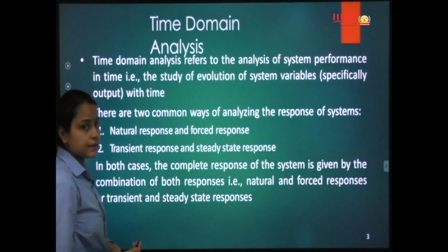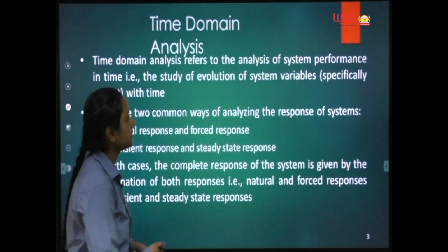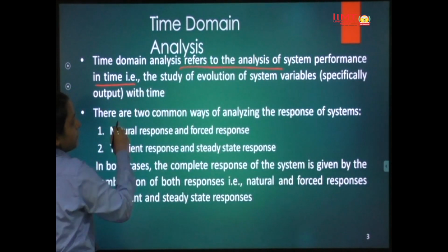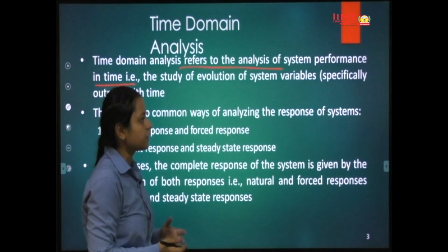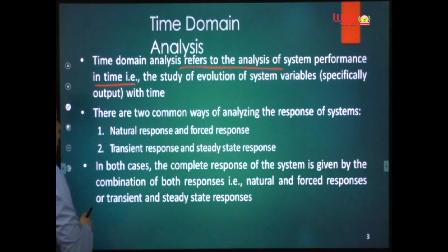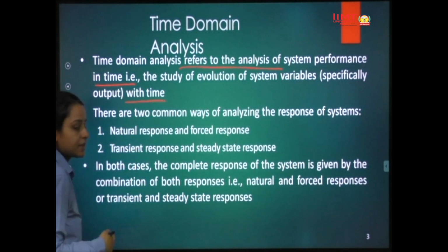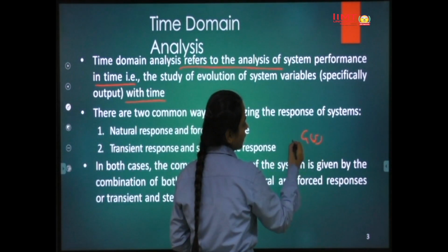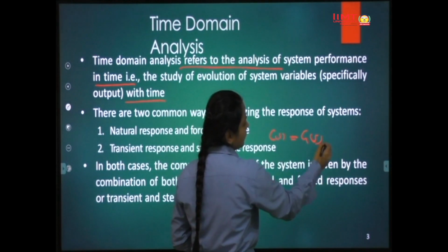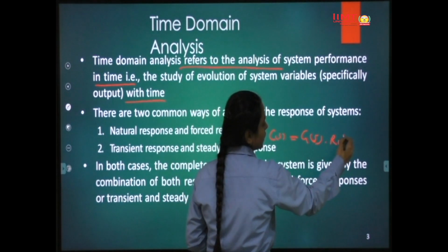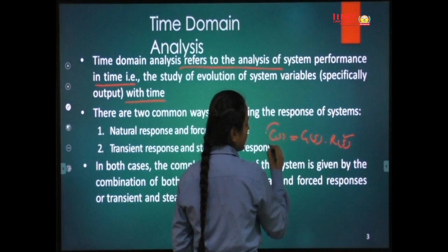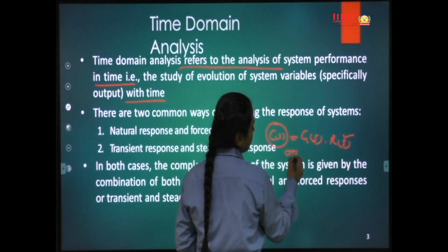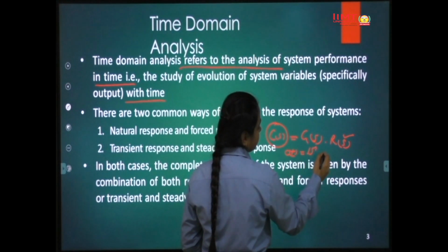So what is basically the time response analysis? It refers to the analysis of system performance in time, that is the study of evaluation of system variables, specifically output with respect to time. So we simply would have a transfer function in S domain and an input in S domain, and then we can calculate the value of C(s), and by taking the Laplace inverse transform we can get the value of C(t).